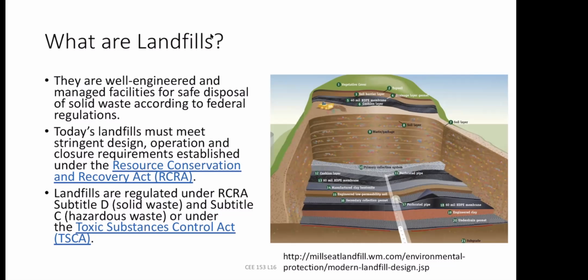That's why, first of all, when you design this landfill, you should put the landfill in a place where the soil is extremely impervious. That means clay soil. Any site which is full of clay is a great site for landfill, because you already learned in the class that clay does not allow water to move through it.